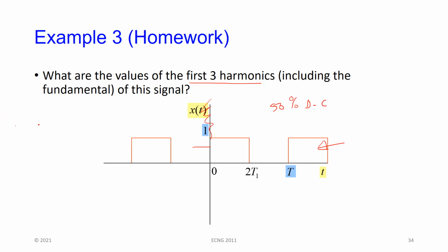If I gave you this just by itself and told you that was a 50% duty cycle, right? Square wave. The harmonics of that are fixed. Once it's a 50% duty cycle, the harmonics are fixed. So whether I look at it here, this is my time 0 when I start to look at it, or here, I am not going to change the harmonics of it.